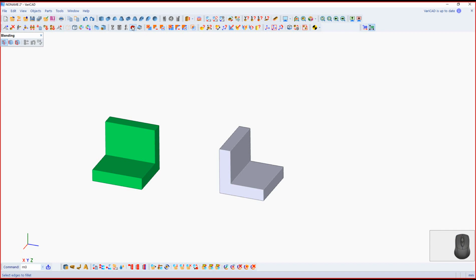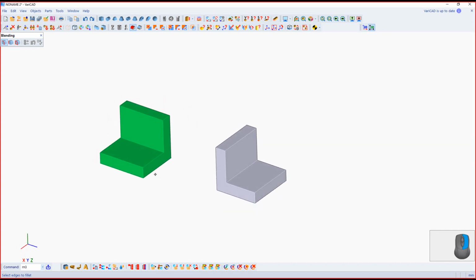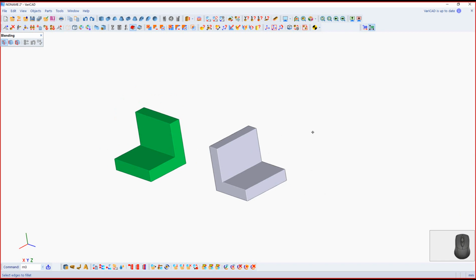Usually this kind of item should be added as the last thing to do on a part, because fillets and chamfers, this final arrangement, sometimes give problems in any software, and it is important to leave them as a last operation, because if we keep doing things on parts that already have fillets and so on, it's not uncommon to see the programs giving errors. Okay.